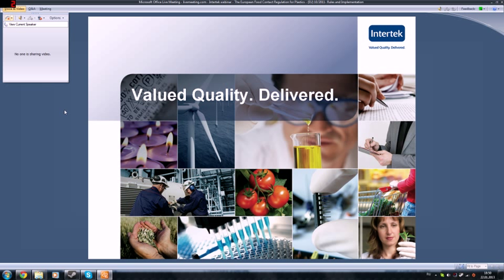Then back to the first question in this line. What about the food contact time and period? Is this what the manufacturer expects under normal use conditions? So how to define the food contact time and the temperature? Time and temperature are related to the end application. So if you know the end application as a supplier, then of course you can choose the material for it which you know is compliant for 10 days at 40 degrees or 2 hours at 70 degrees. If you don't know, you usually take the so-called standard conditions. Standard conditions would mean an average storage time of below 30 days, so 10 days at 40 degrees would apply.